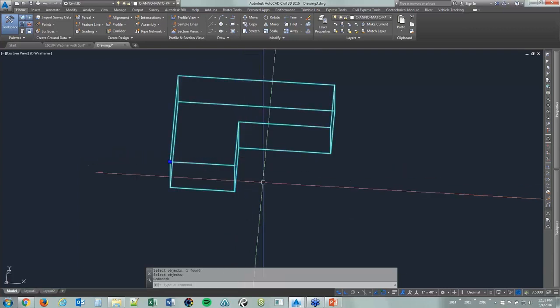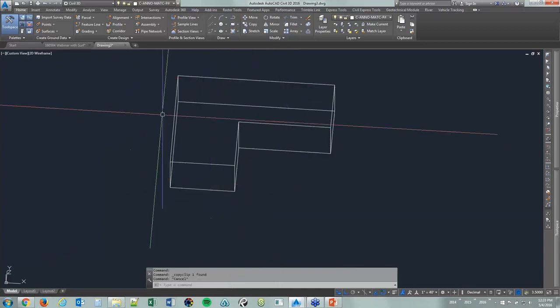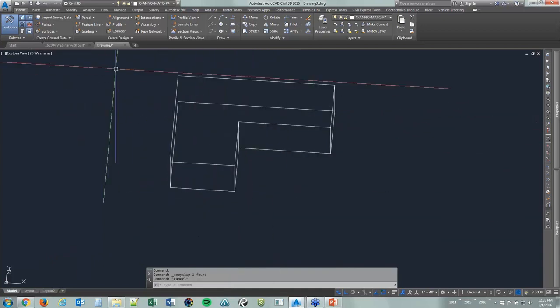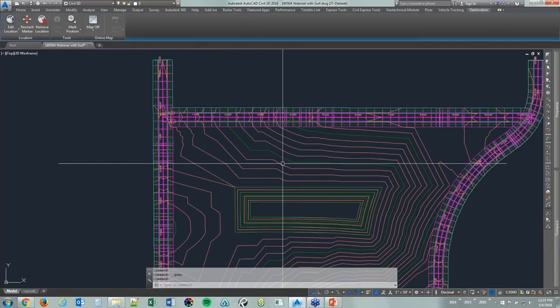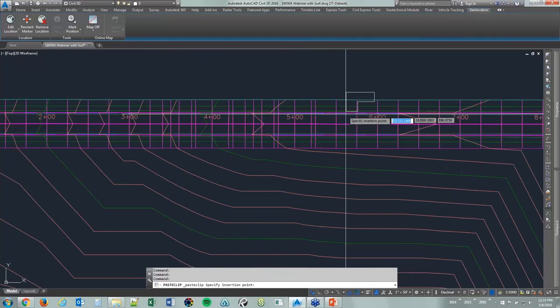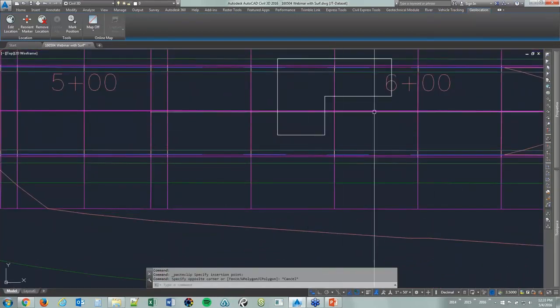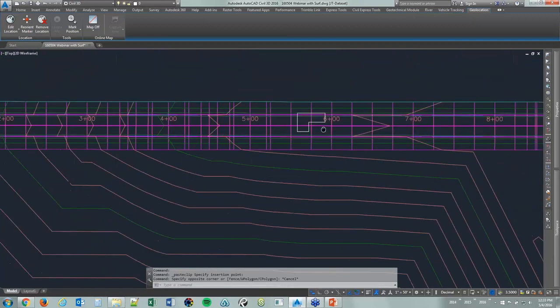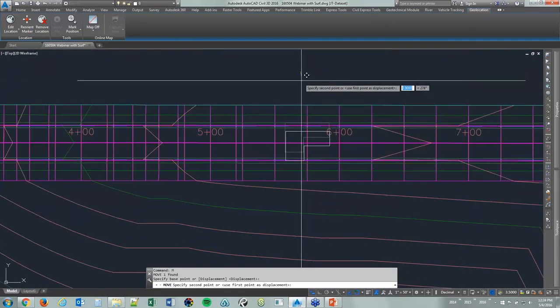Now I'm going to do an AutoCAD Control-C. So I've just copied to the clipboard here. Okay. I'm not even going to save this drawing. Maybe you'd want to save it just in case this object were to move later on. But I'm not going to worry about that here. Do a Control-V. So I'm going to paste this in. I'll paste it somewhere here along that alignment here for the north row. Here I have my object. Maybe I want to move that just a little bit.